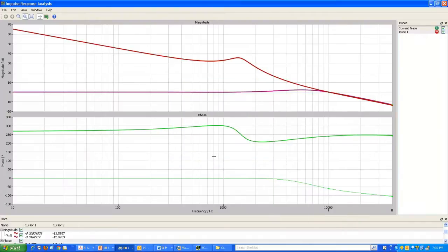All right. So obviously the top one should be the open loop gain or the loop gain, and the bottom one is the closed loop gain, which is 0 dB for much of the frequencies below the crossover frequency. And you can clearly see that after the crossover frequency, the two gains just match.